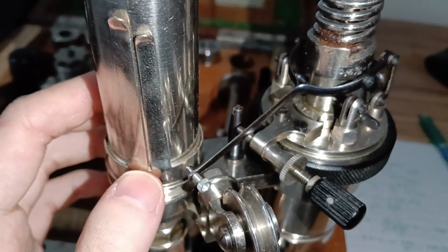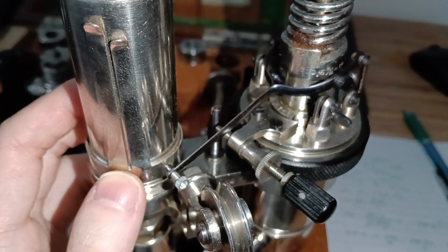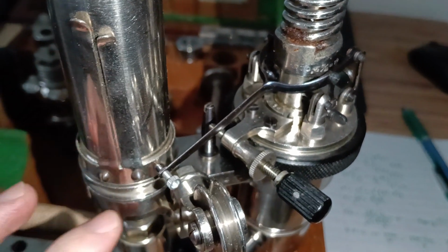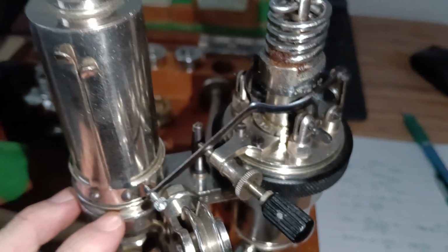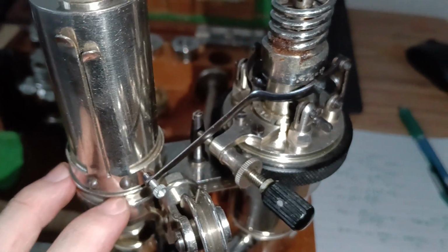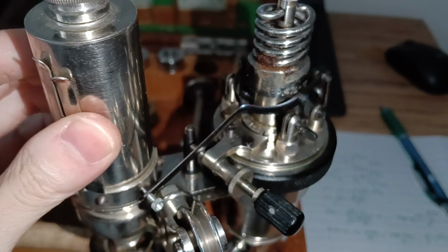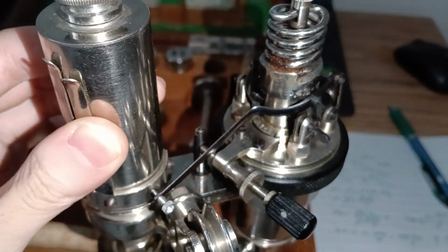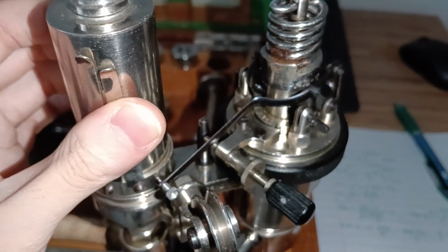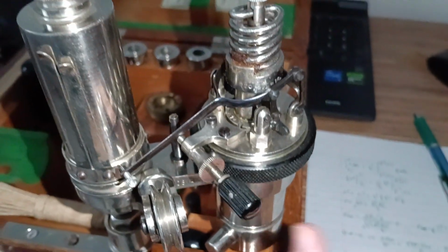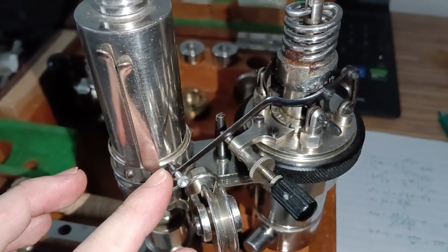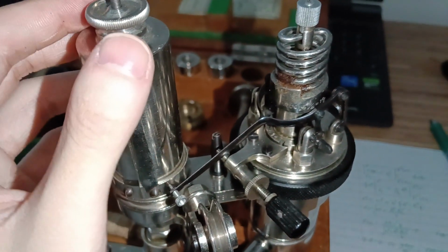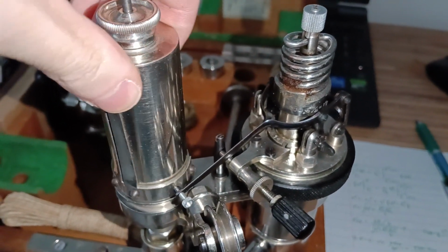But considering if you connect this pulley or this cord to maybe just the piston rod, you will have the downward movement by the piston transferred into the rotation of this cylinder, and you have the pressure measured by this mechanism into the movement of this pencil.